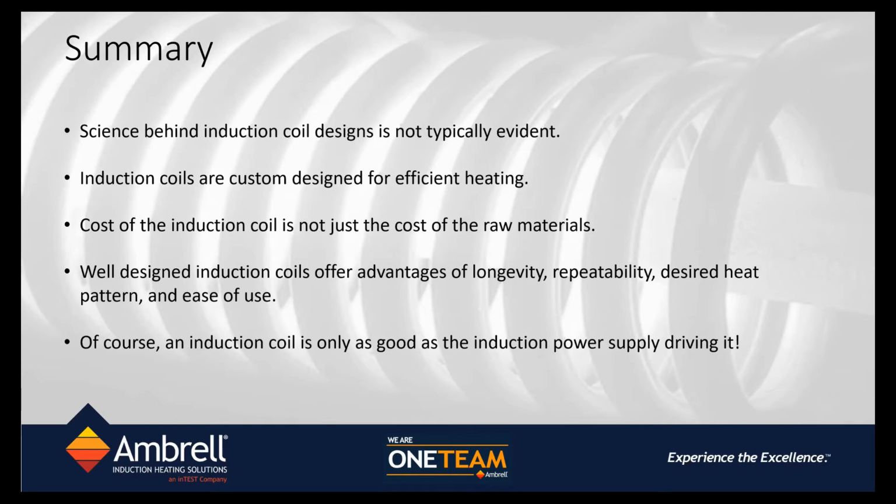With the steels, for example, that are not highly conductive like aluminum or copper, there is not as much change in the frequency. So the circuit is different. And this is where the automatic tuning feature comes in so handy, that we don't have to worry about it. The induction heating power supply automatically detects what the material makeup is inside the coil and automatically resonates to the resonance frequency to deliver the energy.